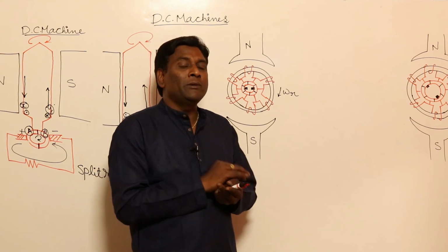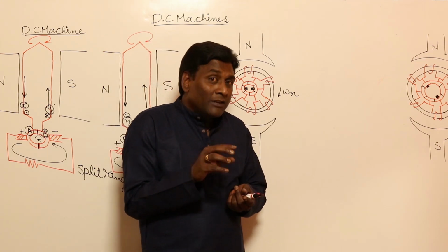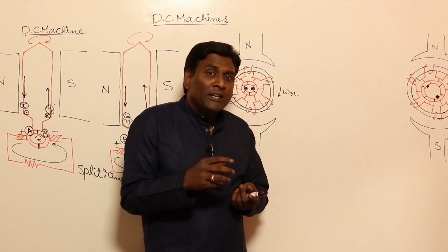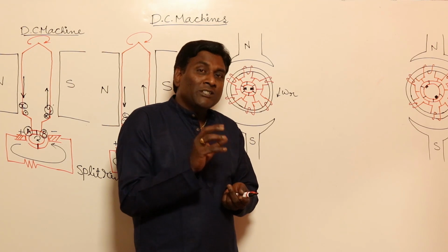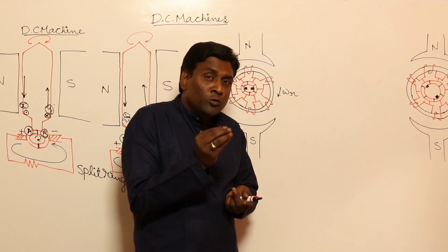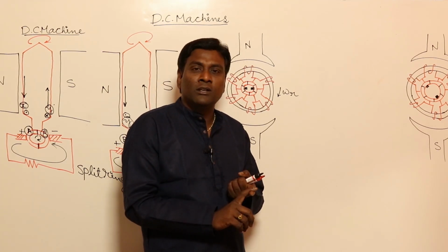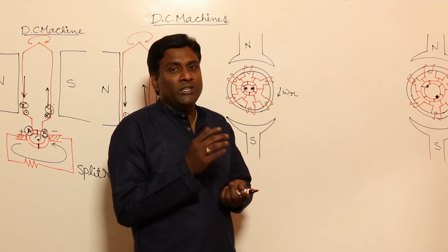the number of turns to be provided in order to produce rated voltage is going to be increased. So the volume of copper is increased, meaning we are investing more money. Yes, but still we invested more money in the synchronous machine in order to make the flux more sinusoidal and the induced voltage more sinusoidal.